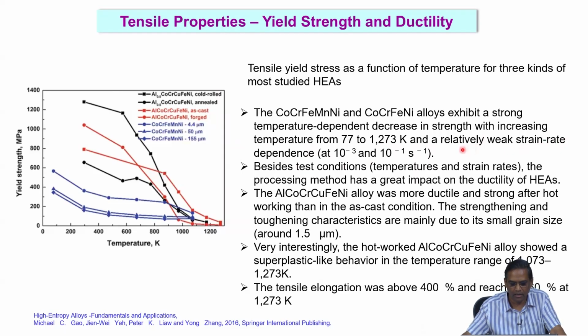So, the strain rate dependence, right, the material is sensitive to strain rate or not. This is also important, because why is this important? Strain rate sensitivity. Why is strain rate dependence of the material important? Sure, strain rate sensitivity, yeah. So, it is basically resistance to necking. So, the deformation rate is controlling that, okay, especially at high temperatures.